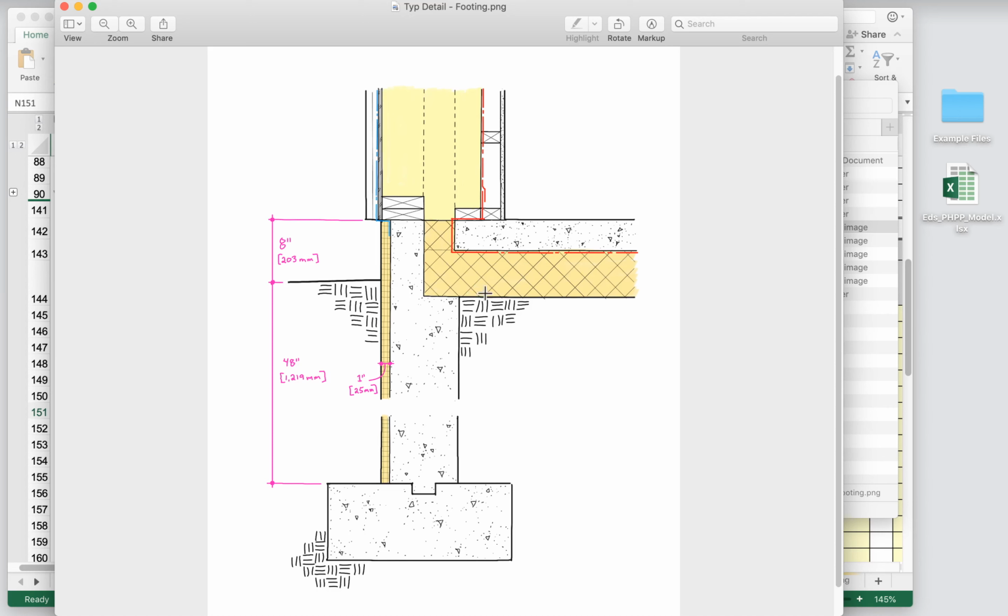So what do we have though? Well, obviously we have our insulated floor slab, and we have our double stud wall. We have this frost wall here, and notice that we have something of a haunch here, which is actually supporting the load-bearing stud wall on the outside here. We've got the insulation that turns up in a nice continuous fashion. So we do have some constriction of the insulation. There is some thinning of the insulation at this point, but overall, I would say we've got pretty good insulation continuity right here. And so if we are actually able to build it that way, I think, just as an estimate, it will be in pretty good shape.